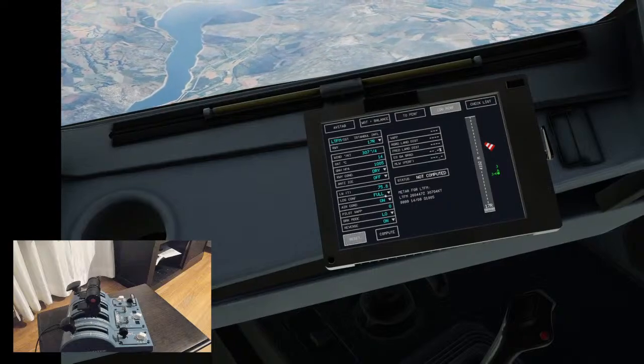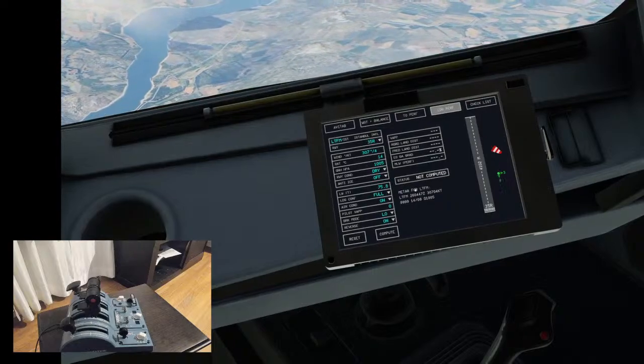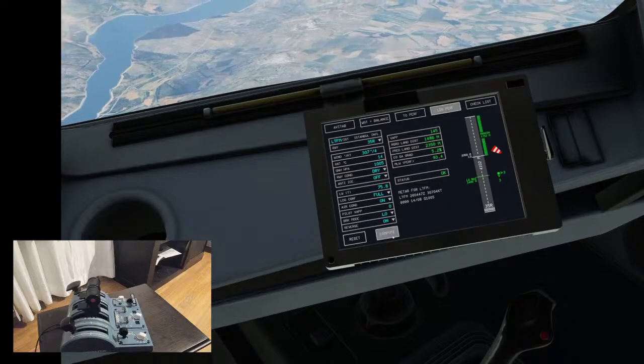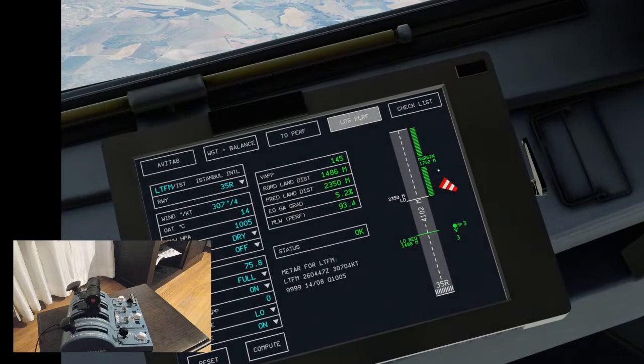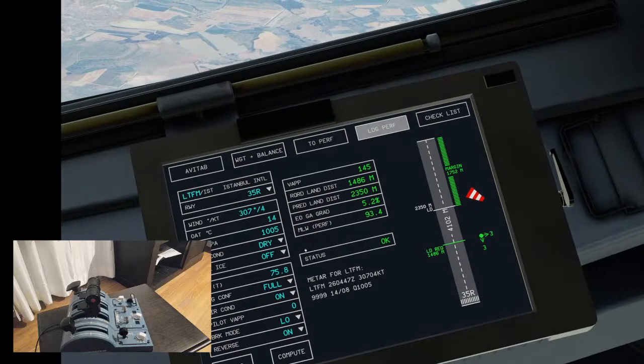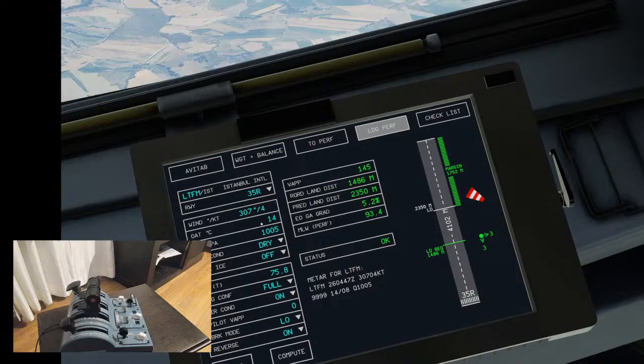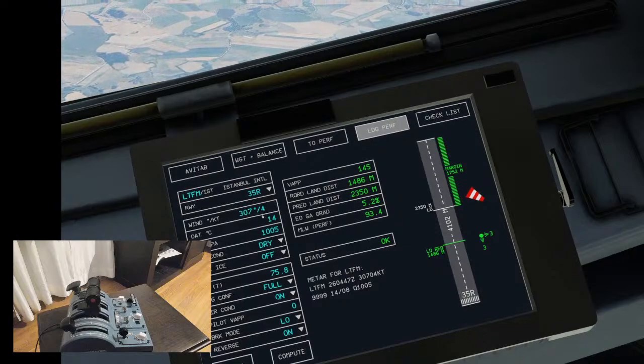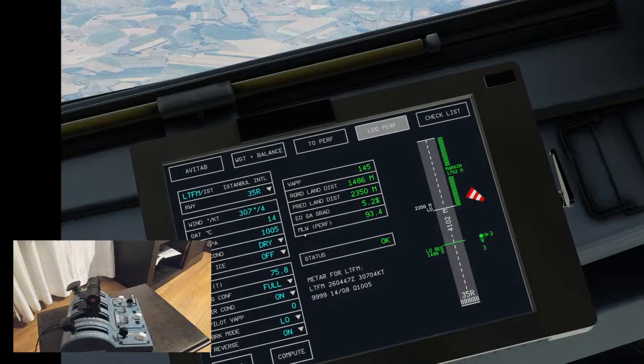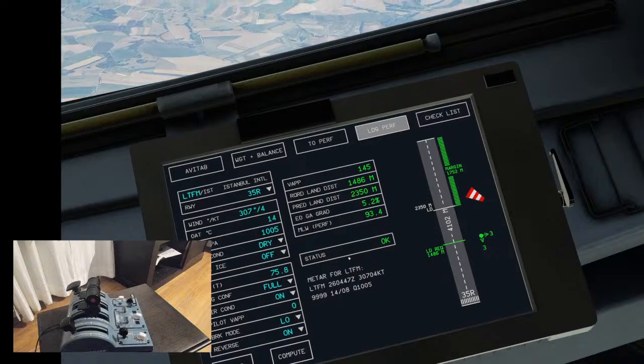Landing, yes, reset. Here is runway 35 right. And the direction of the wind, as you may see, is coming from 307 degrees at 4 knots. It can be negligible wind speed because it's very low. Up to 10 knots we can add 5 knots to our final approach speed.